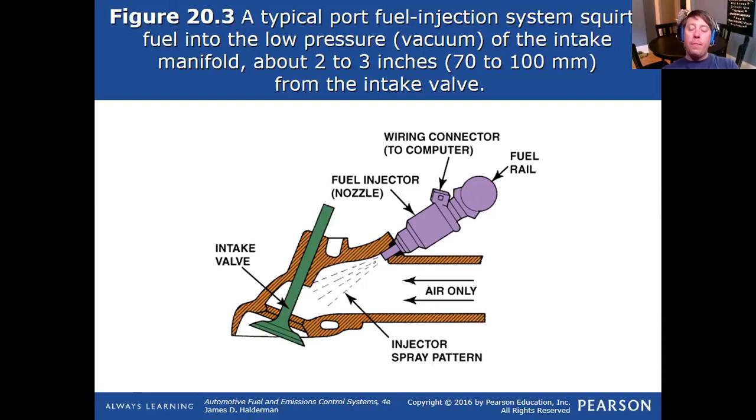that the fuel injector, if it's designed to spray 20 pounds of fuel per hour, that's typically how we rate injectors, like how many cc's in volume per minute. There's some sort of weight of fuel over time. There's a maximum amount of fuel that an injector can deliver, and that number is based off of pressure. And in addition to the pressure, the vacuum is also a factor in that flow rate for that fuel injector.